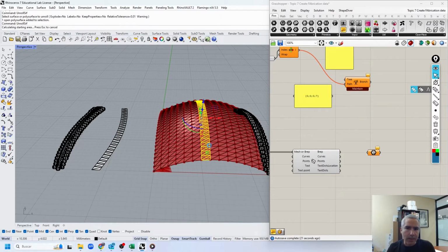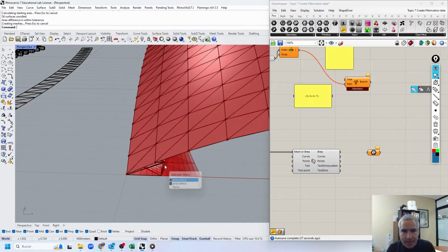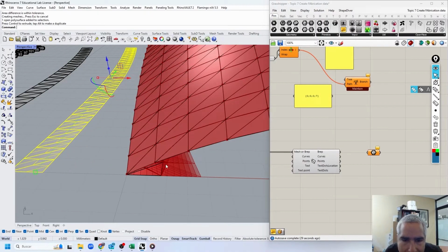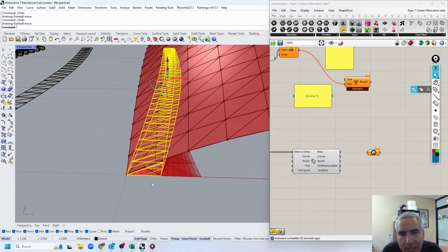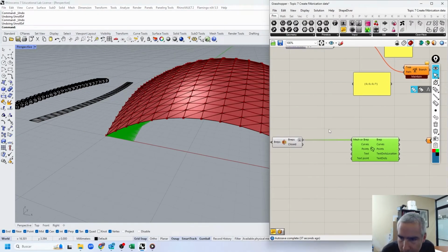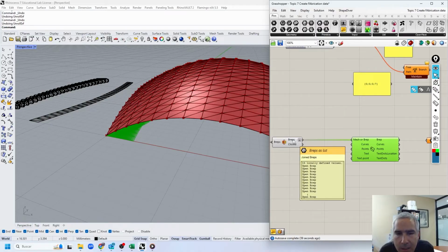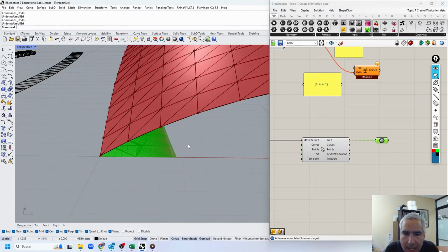And yeah, if you do that for each one of these, they will always be put inside the 0, 0, so you'll have to manually move them around. But really what Open Nest is doing is just putting all of them right here. As you can see, I have 15 joined B-reps, and out of here I have 15 unrolled B-reps that come out as a tree.